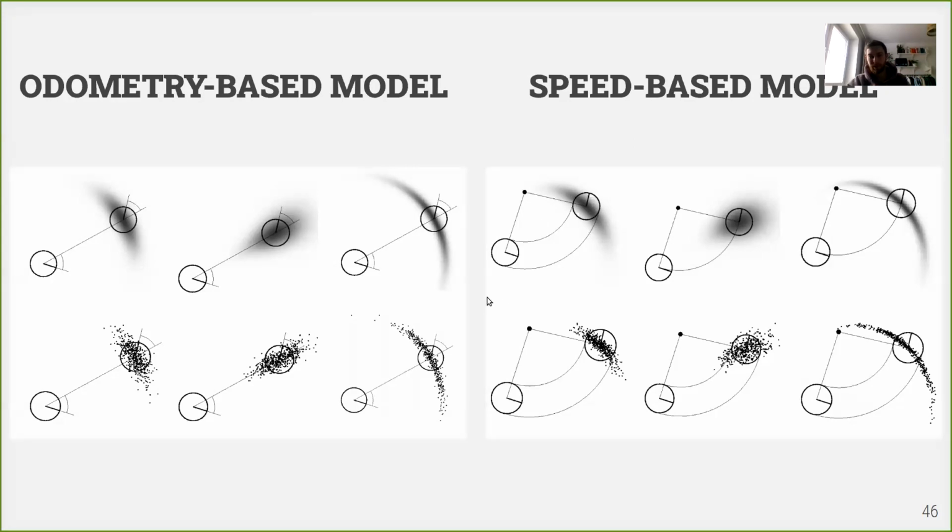Since it is a recursive estimation, every step we are losing some information with motion. So we move, we become less certain where we are, and then we correct it with external sensor readings, and then we move again and again, lose some information, gain some information, and so on. This is like an infinite cycle when we work with robots which move over space. They always become less certain, and then with sensor readings, they become more certain where they are.